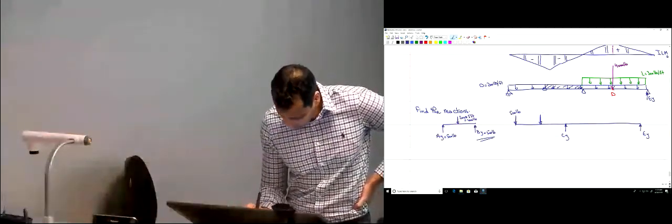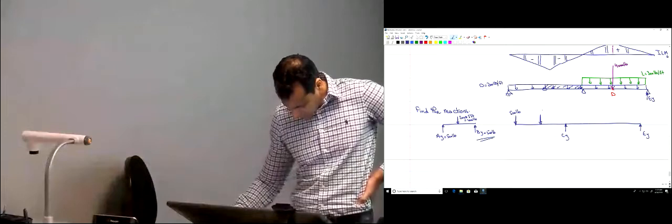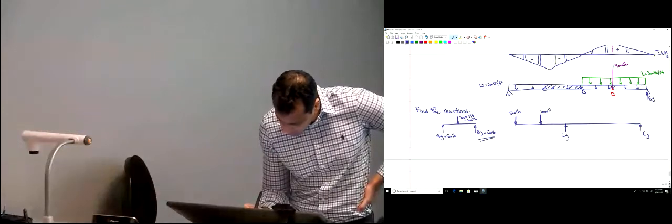Okay? Here, this gets inverted. So here we have 500 pounds, the inverse of the BY over here. And then here we have the support, this is CY. And here we have EY. And here we have this uniform load, this part here, which is 300 times 5. So this is it? No, 200, sorry, that's the dead load. So 200 times 5, so that's 1,000 pounds.